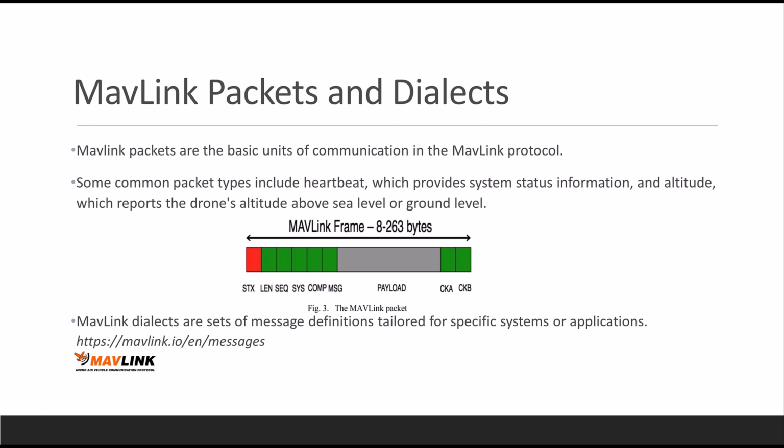What is more interesting for me about this MavLink frame is that many of these frames are being sent and received at the same time. For example, you are sending the attitude data with this MavLink frame 10 times per second, and in the meantime another MavLink frame called, for example, heartbeat is being sent at 1 Hz, and none of these are blocking each other.